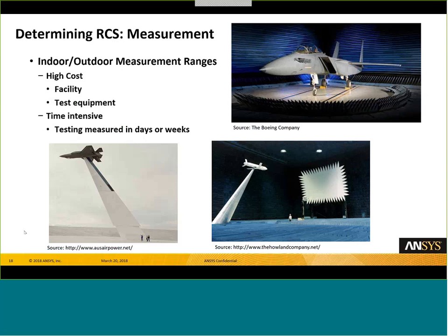So how do we acquire RCS data? Testing is still a very important part of the process for characterizing or certifying RCS. The downside, of course, is really in the area of cost. For those of you who are fortunate enough to have a facility that you can test in, you're aware of the extreme effort it takes to certainly make a chamber and keep the chamber quiet. There's maintenance involved in ensuring that the RCS measurement is not unintentionally picking up effects from the chamber itself.